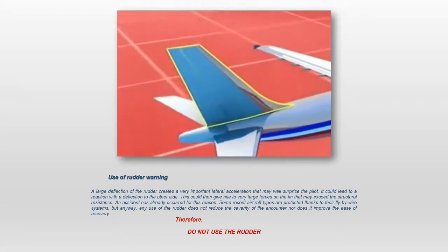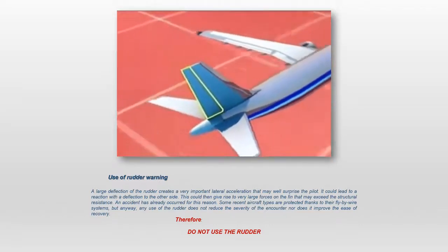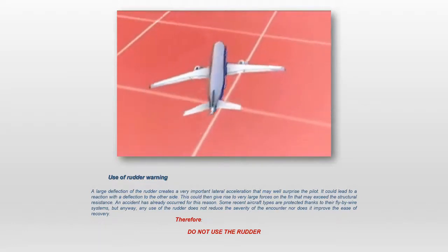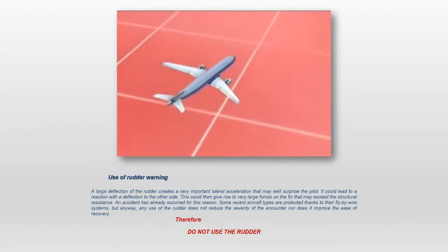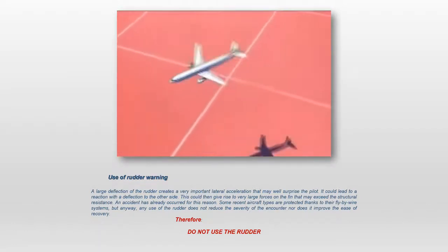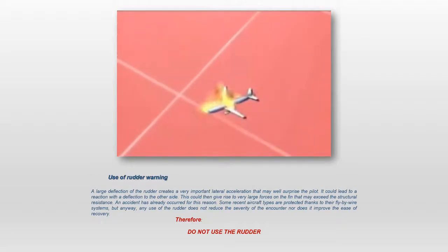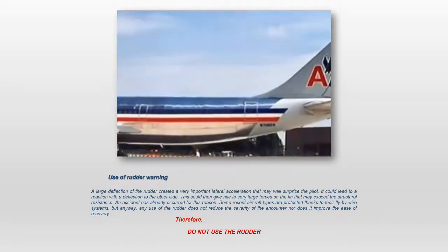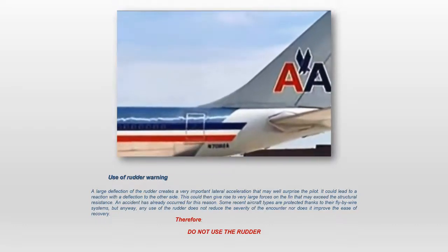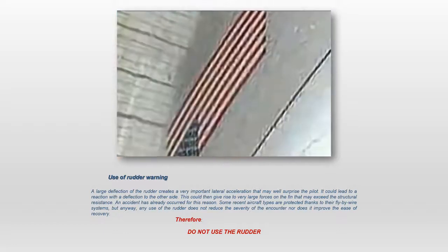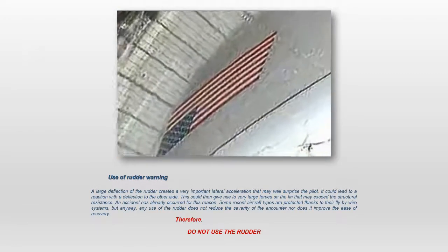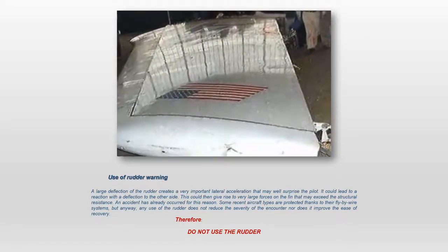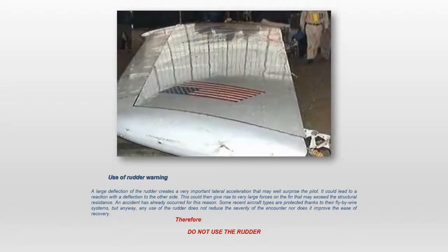An aircraft's vertical stabilizer, which includes the rudder, provides lateral stability during flight. Take it away, and the airplane will wallow from side to side, lose altitude, and crash. Flight 587 was on an Airbus A300-600 aircraft. The vertical stabilizer had a unique quality. It was manufactured from composite material, layers of carbon fiber that provide a lightweight alternative to aluminum.